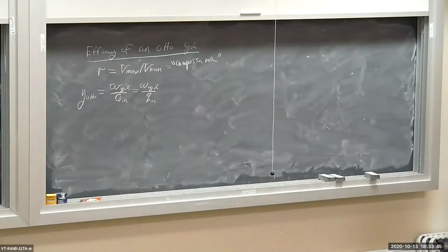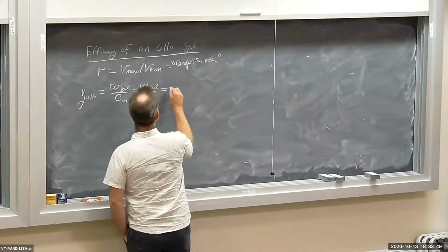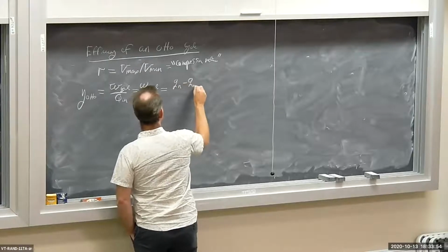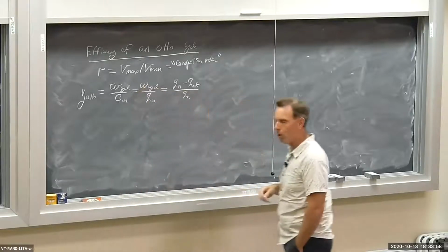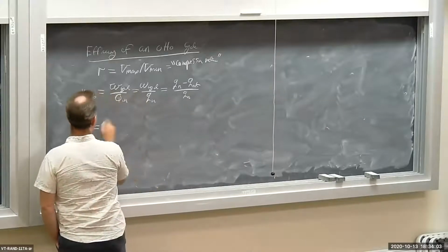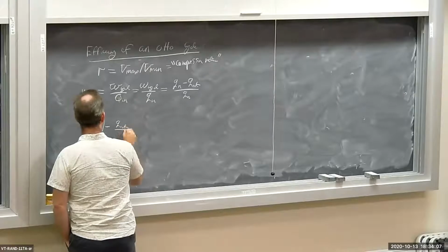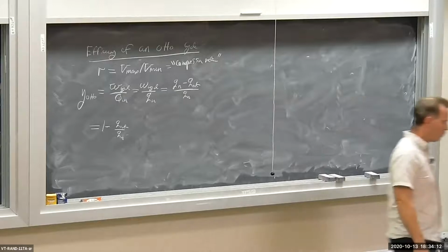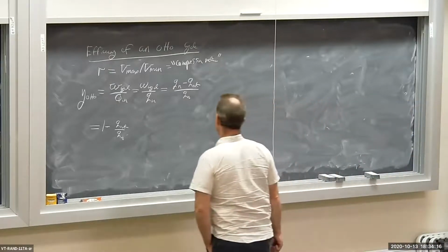Now the cycle work is equal to the difference between the heat transfers. So W cycle is actually Q in minus Q out. And of course, I'm dividing that by Q in. Okay? And you do a little bit of algebra here, very little. You get 1 minus Q out over Q in. Now let's figure out what these Q outs and Q ins are.